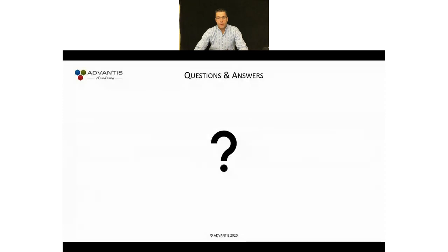What kind of new revisions to ASTM are happening at the moment? Well, as I said, F24 has about 20-plus different standards, and there's constantly work in progress going on in all of these standards. And normally each of these standards is being published once a year. So you see F2291 is the main design standard, and then -20 means version 20. Sometimes there's a 20A and a 20B, so there could be one coming out in springtime and one in the fall.